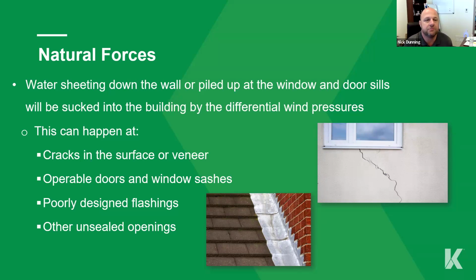Doesn't mean there's necessarily spalling yet. But when we leave those cracks unattended, so we're not actively sealing them, keeping that water out, is when you get the deterioration. It's a lot worse in a wood frame building, in my opinion, because you can't see it as well as spalling and things like that.